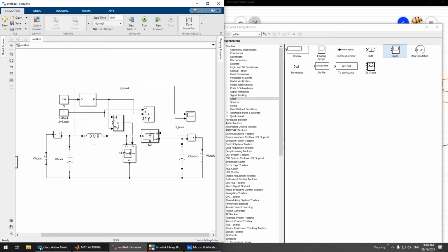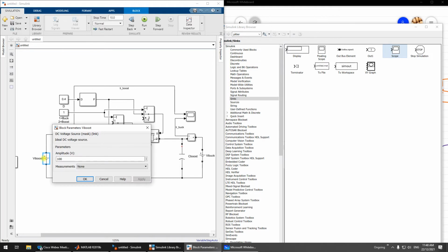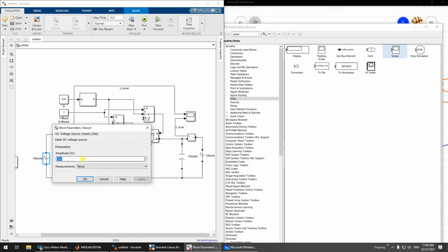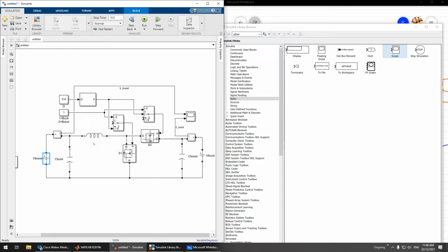Okay, if I run this, it doesn't work. Why? Because the voltage is the same at first. Let us check. So the voltage here needs to be lower, maybe 50. Actually there should be a calculation here, but I just use trial and error. Another thing you need to consider is that a voltage supply and a power converter cannot operate in parallel.